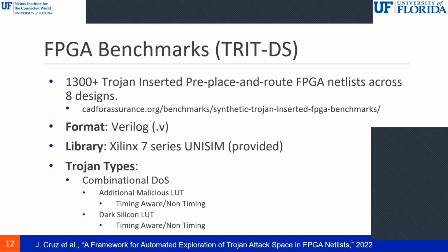We have 2 main types. We have this malicious LUT, which is almost akin to the ASIC level, adding additional gates. But then we have dark silicon, which is specific to the FPGA abstraction. And we also have timing-aware and non-timing-aware variants, which I'll get into.